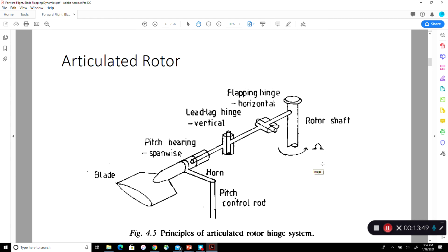So they have a very elastic bending rubber-like connector that connects the shaft to the rotor, free of any hinges. It gets rid of all the maintenance. But this region does see a lot of stresses, so stress fatigue and stress failure of that connector is of concern also.